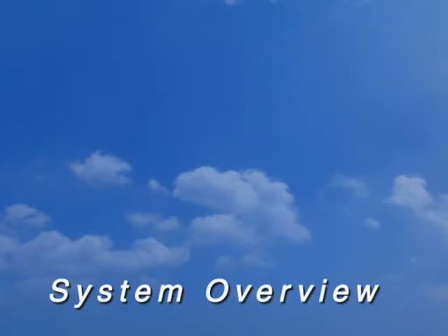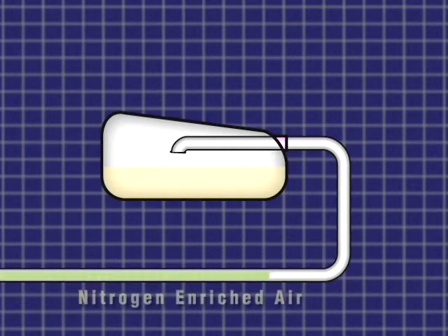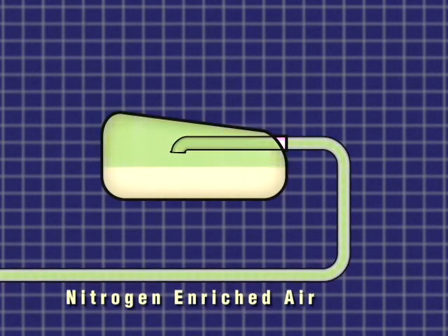The nitrogen generation system replaces the empty space at the top of the center wing fuel tank with nitrogen-enriched air, or NEA. This reduces the flammability of the tank because NEA contains much less oxygen than regular air. But where does that NEA come from?